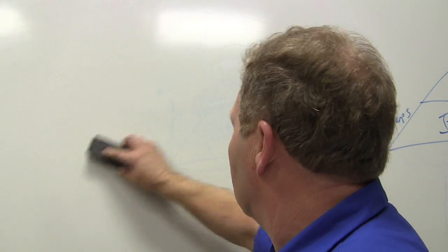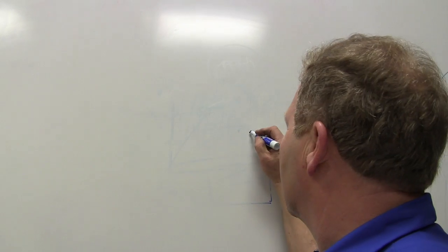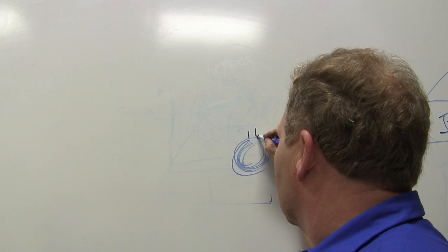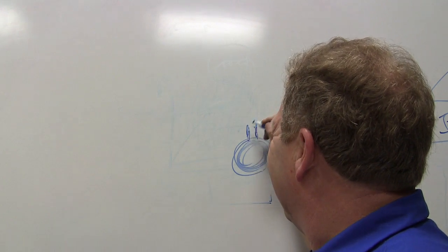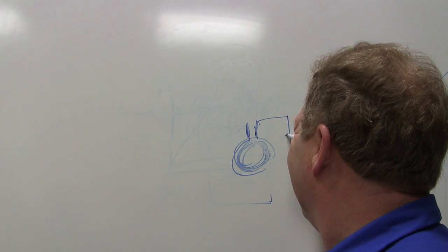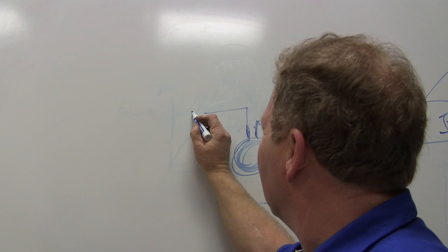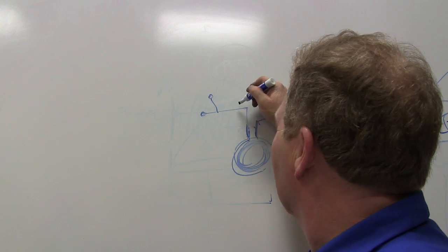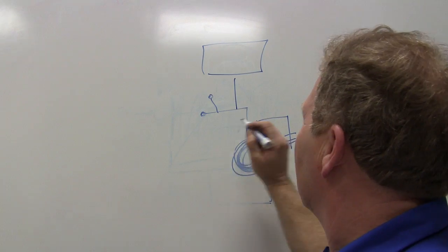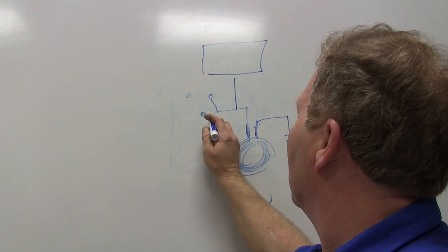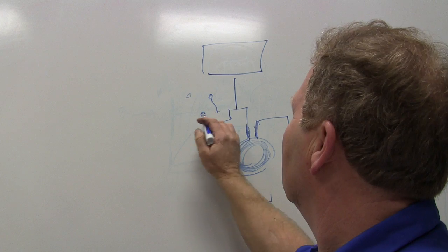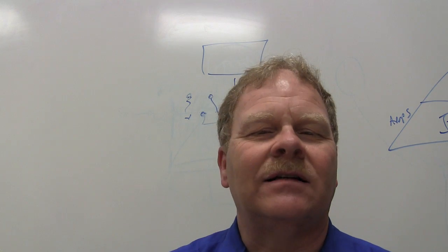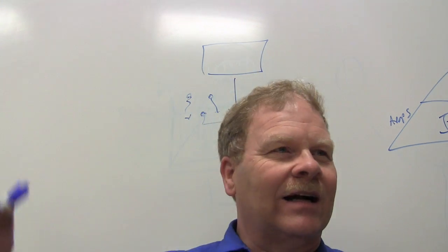I need to explain that too while we're here. I've got an AC compressor clutch here, and it's got lots and lots of windings in here. Right here I've basically got ground, and this right here is coming from a relay, and this right here is going to the PCM. If the PCM tells the relay to open up, and the relay opens up, whenever you have all that magnetism sweeping across that coil, it collapses that field.